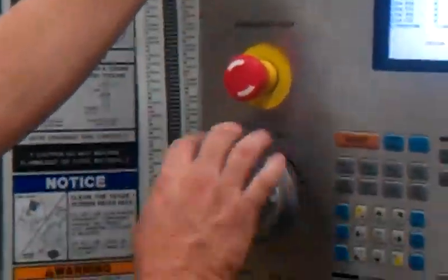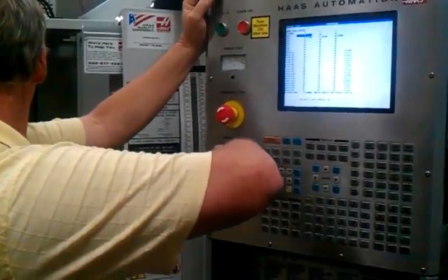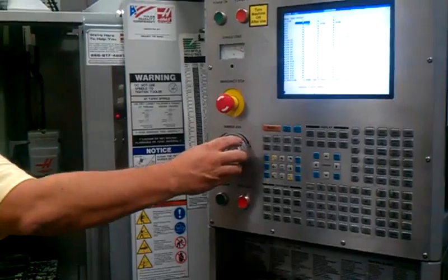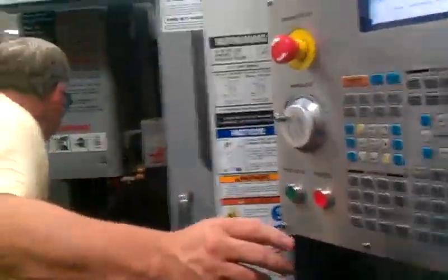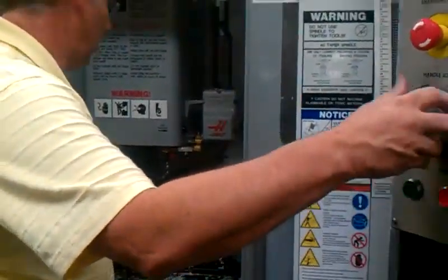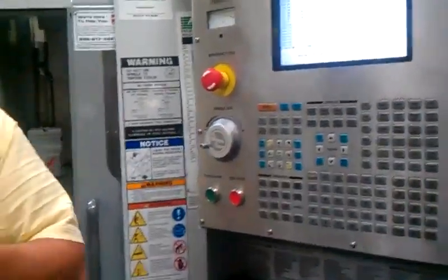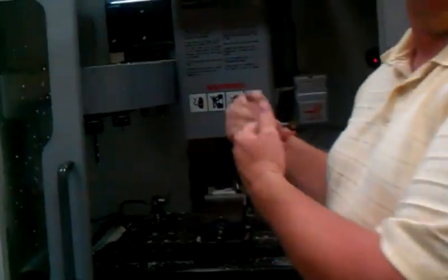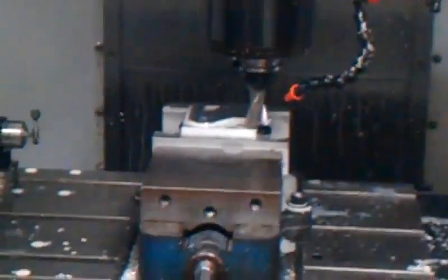At the bottom right hand corner of the part. I'm by no means being accurate here, guys. I'm just getting close. Everybody agrees if I use an edge finder I'd be much more accurate, but that's pretty much the center of the spindle at the bottom right hand corner of my part, right? So if that were my part program 0, that's where I wanted to program from, I could actually set a